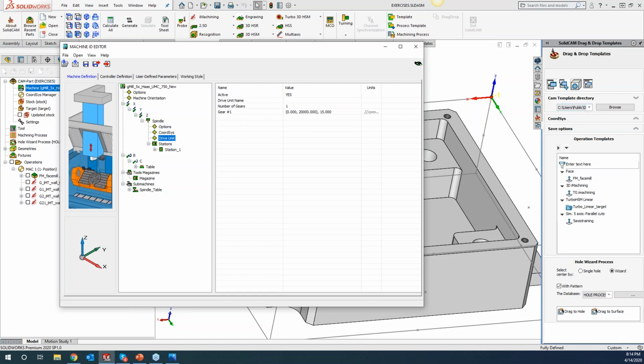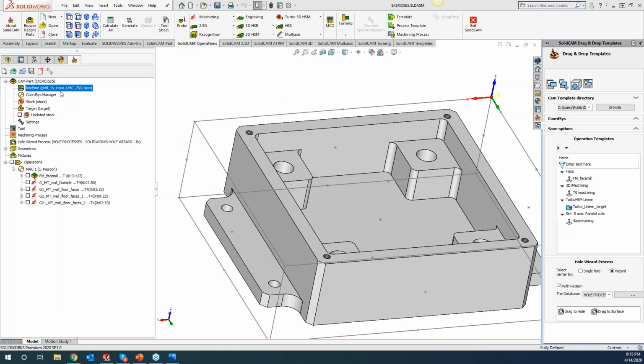Yeah, absolutely. For example, for anybody that has a Mazak Integrex style machine, where you have the B-axis milling head on top, which has a much more powerful spindle than what you typically get with a live tooling turret. Usually those live tools on a turret are very low in horsepower, whereas you get a real milling spindle on that B-axis head. So this will allow you to get the most optimum speeds and feeds out of iMachining for both cases. Yeah, perfect.